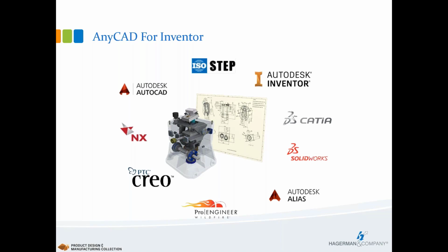So if you've got Inventor 2020 Update 3, you could insert Inventor 2021 files. If you've got Inventor 2016, you could place Inventor 2017 files, as long as you have the latest and greatest updates. So Inventor does allow you to place one release newer than your version. 2022 is the latest and greatest, so I can place any version of Inventor files in here.